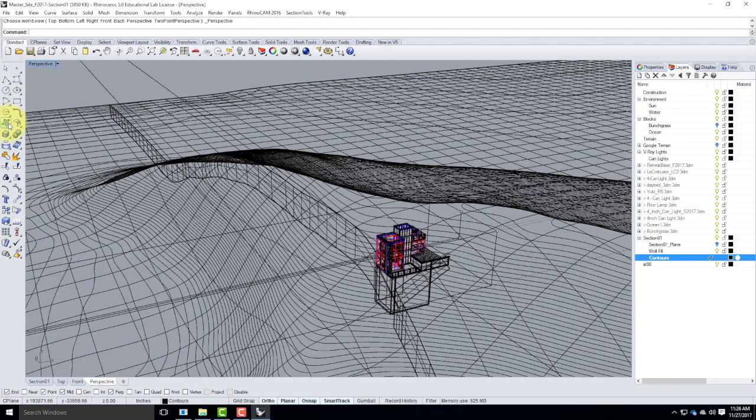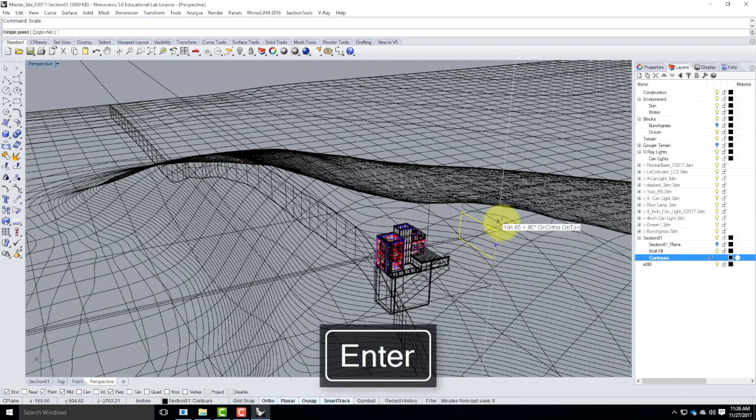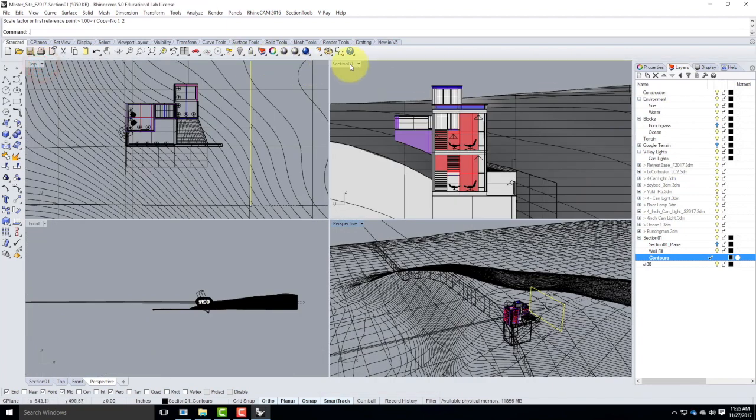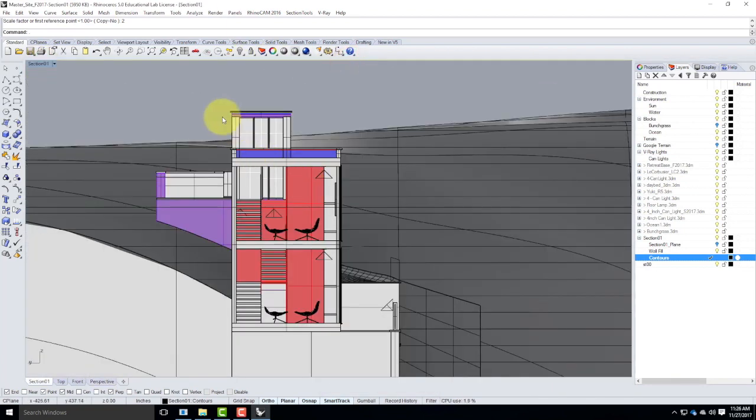I'm going to go ahead and draw my rectangle. Remember, it's not a surface, it's just a regular rectangle. 3 points. I'll go from there to there to there. I'll select it and then scale from this corner by 2. There we go. That's set up. I can then move back into my section 01 layer. I have that rectangle set up.